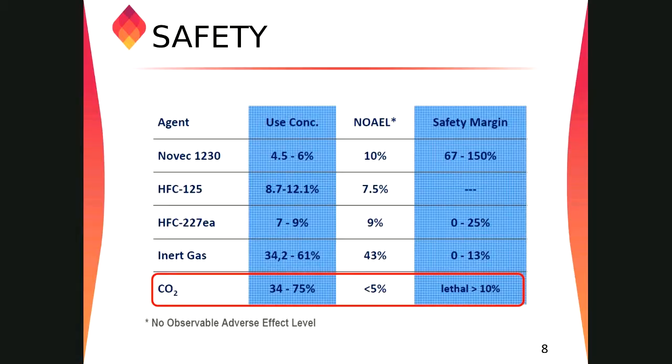The problem with the CO2 system is that when it discharges into the room in case of a fire, it will replace the oxygen. The room becomes full of CO2, so no one can survive in those conditions. This is the reason why building codes and safety bulletins say CO2 is not allowed for manned locations, meaning areas where persons are present.